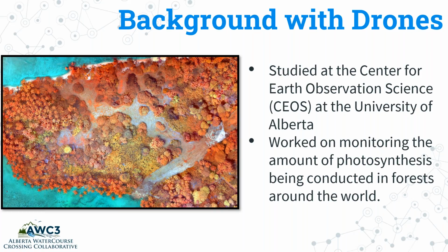So just so that we all are on the same page as to what photogrammetry is, it is the science of essentially turning 2D images into a 3D model or a 3D point cloud. And what photogrammetry does is that essentially as your drone flies in a transect, it is going to be taking multiple pictures with some degree of overlap between each photograph.